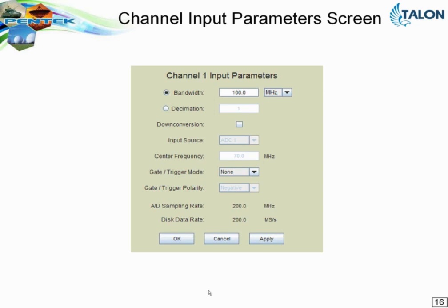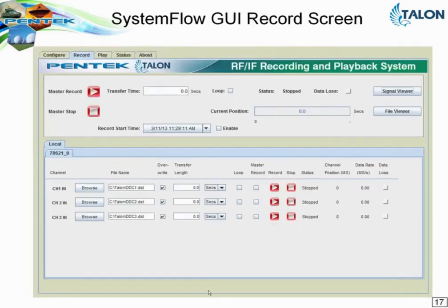One class uses the 200 megahertz 16-bit A to Ds and either 800 or 1.25 gigahertz 16-bit D to As. So you can have up to 8 channels of either one connected in a chassis, connected through the system to a RAID controller, also with digital down converters and digital up converters as part of the signal path. So these come in different form factors, the commercial, the rugged, in the portable, and the rugged rack mount, and then at the lower right you can see the extreme, the RTX.